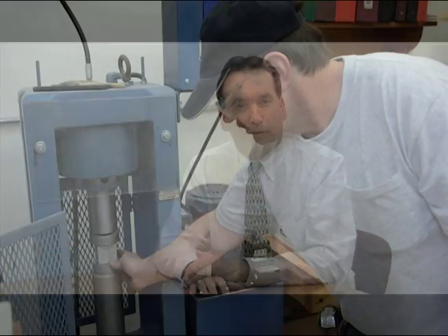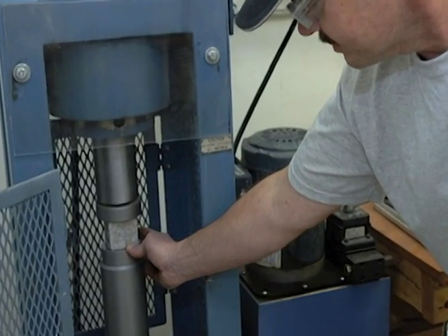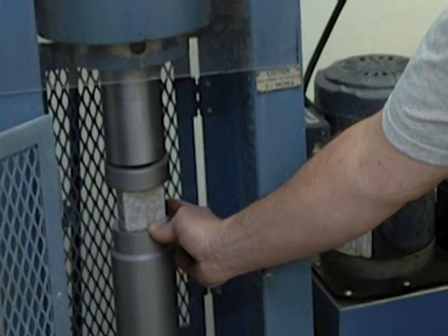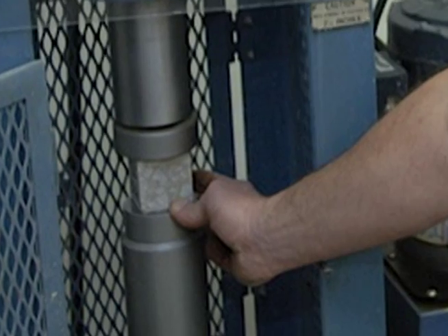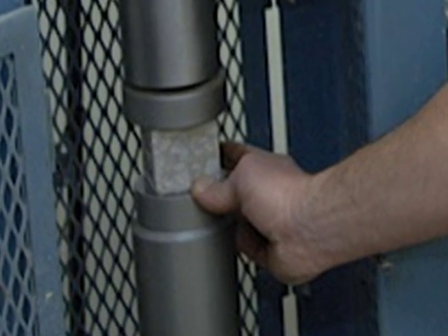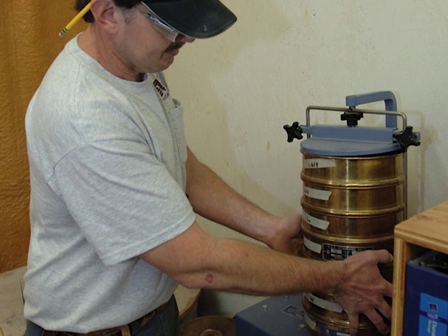The product testing is pretty involved. Our members are actually required to test their product for every 500 cubic feet of material that they produce. They are testing the material for compressive strength to make sure that it meets 6,500 psi. They're testing it to make sure the absorption is less than 6%. They're even testing their product to make sure that it passes a freeze-thaw durability test. Again, all of those are really aimed at making sure that it's a premium quality product that is going to sustain itself over time.